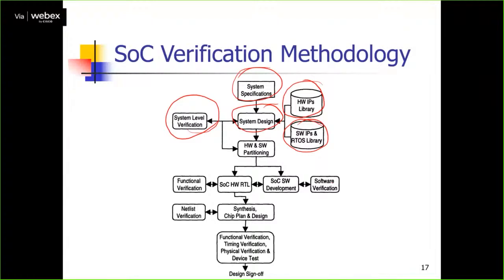So you do the functional verification: pre-routing, post-routing, pre-CTS, post-CTS, pre-synthesis and post-synthesis. This is the pre-synthesis functional verification, and this is the post-synthesis functional verification.